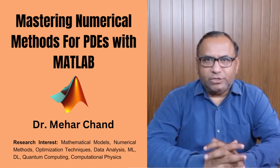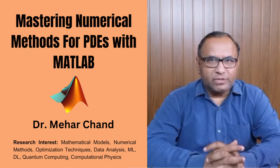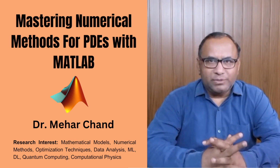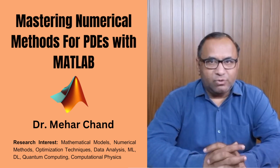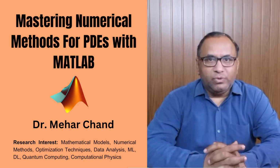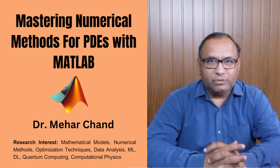Welcome to today's lecture on solving the two-dimensional heat equation using the finite difference method, both computationally with MATLAB and manually. The two-dimensional heat equation governs the distribution of temperature over a 2D region as a function of time, influenced by thermal conductivity and initial and boundary value conditions. We will explore how to discretize this partial differential equation in space and time using finite differences, constructing an iterative scheme